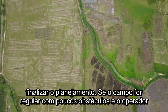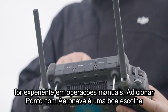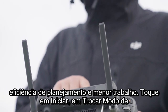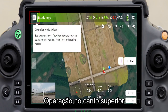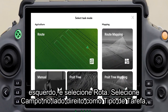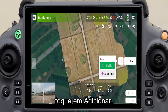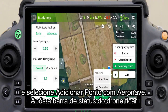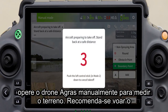If the field is regular with only a few obstacles and the operator is experienced in manual operations, Add Point with Aircraft is a good choice for its higher planning efficiency and less work. Click Begin. Click Operation Mode switch in the upper left corner, and then select Route. Select Field on the right side as the task type, click Add, and select Add Point with Aircraft. After the drone status bar turns green, operate the Agras drone manually to measure the farmland.